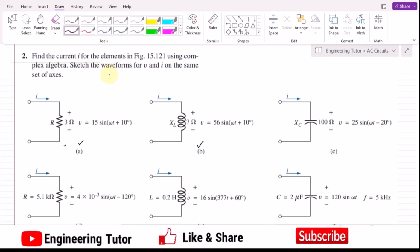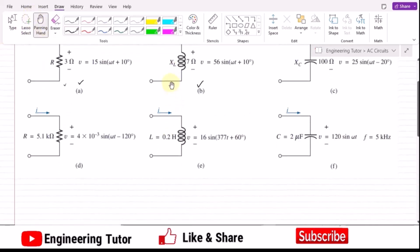Okay, so let me start it, and let me go down. Here in this part C the value of X of C is 100 ohm, and the value of voltage is 25 sine of omega t minus 20 degrees. So what we have to find out is the value of current, and then we have to plot the voltage and current over the same axis.